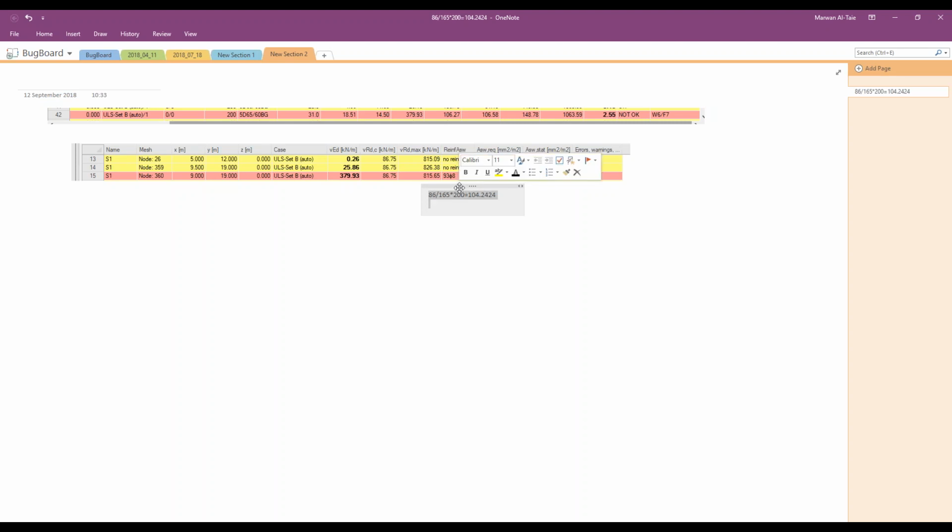So my point from this comparison is that not only does the participation of the steel fiber help you, but if you decide not to put traditional reinforcement in your system, you can use the full height of your cross section, and this will give you a higher VRDC value.